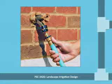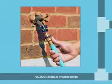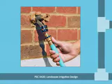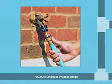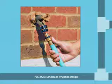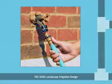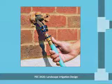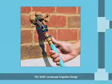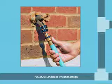In an irrigation system, flow of the water is going to be dependent on the number of sprinklers or drip emitters that are working at the same time, so in a given irrigation zone or area. Each segment of pipe in an irrigation system can have different amounts of flow. And in the case of overhead spray or rotor type irrigation, that flow is commonly measured in gallons per minute. Or in the case of drip irrigation, that flow is commonly measured in gallons per hour.